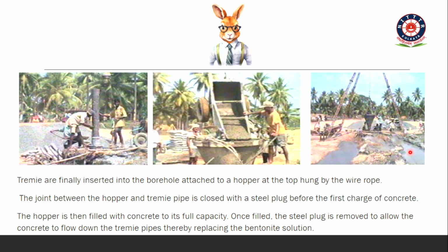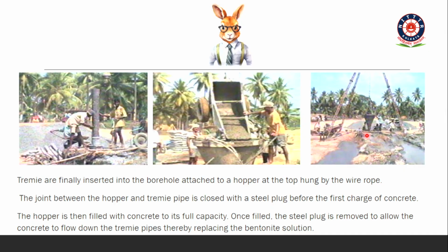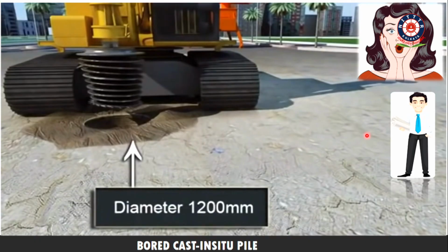See, this is again a thumb rule concept. In case the bore hole collapses while doing concreting, then concrete consumption will be more and this overflow won't be seen. This method which I am trying to explain, the DMC method, is a completely indirect method of identifying the bore hole depth, the required depth. For that you require a skilled supervisor or skilled engineer, and also proper soil verification. Rock at the respective depth plays a vital role.